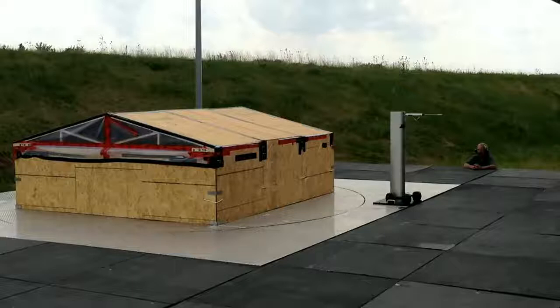At 10 feet by 10 feet plan by 3 feet in eave height, the structure is a 1/3 scale model of a typical 10 meter by 10 meter by 3 meter in eave height gable roof house. The model roof has been specifically designed to emulate the behavior of the corresponding full-scale structure under similar wind loading conditions. This is achieved by reducing the cross-section of the roof truss and sheathing components while selecting a smaller nail size for the toenail connections.